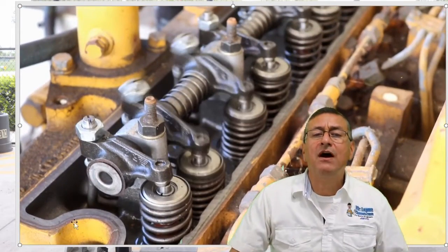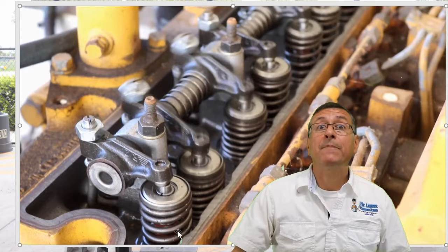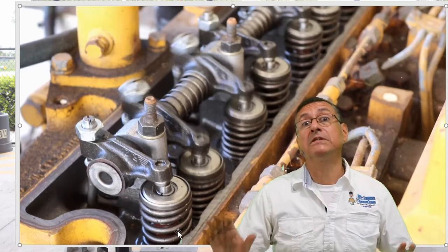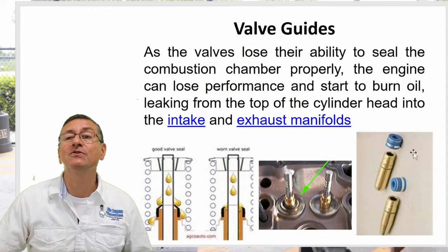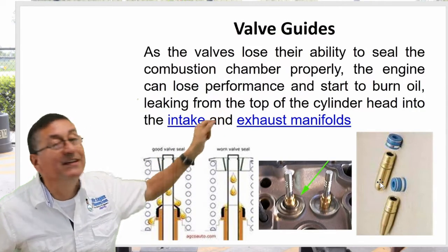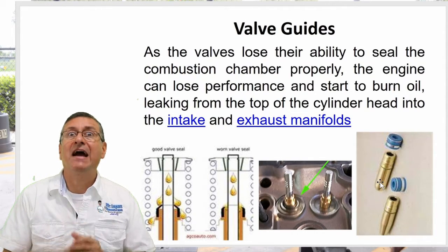My friend, if you have oil in this area, it's possible that the oil goes down here and penetrates into the combustion chamber. Yes, this is possible if you don't have those seals. You remember those seals? The blue ones? Those are the seals of the valve guides.